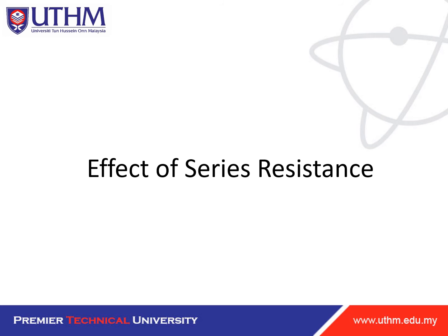Therefore, evidence shows that a small increase in Rs can be detrimental to the performance of a PV module due to the power loss. The current-voltage measurement can be used to quantitatively evaluate the increase in Rs. These measurements are also sensitive to changes in module shunt resistance and other cell parameters.